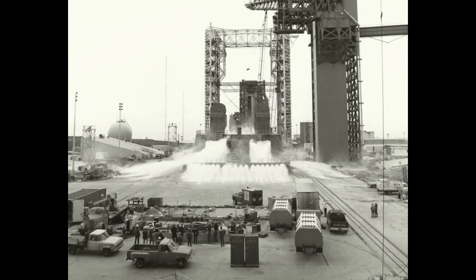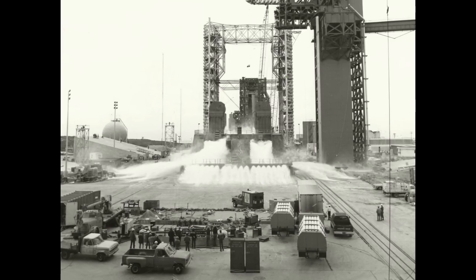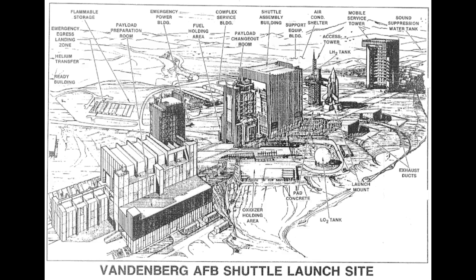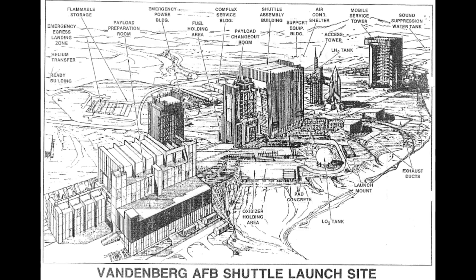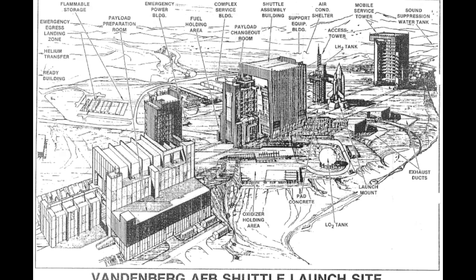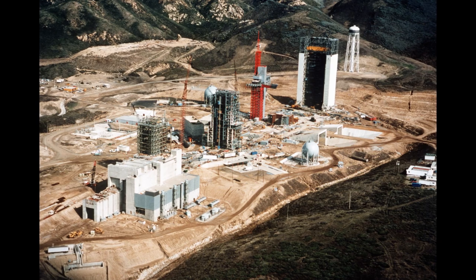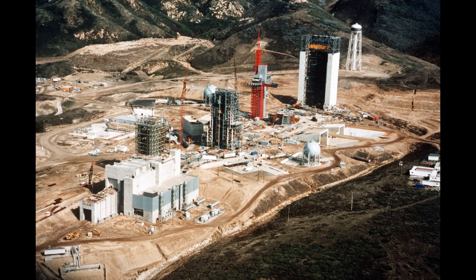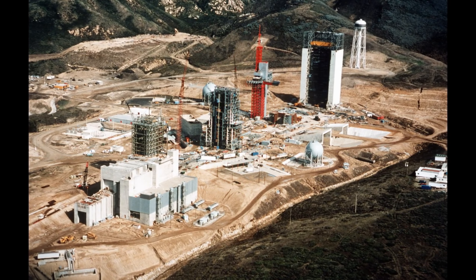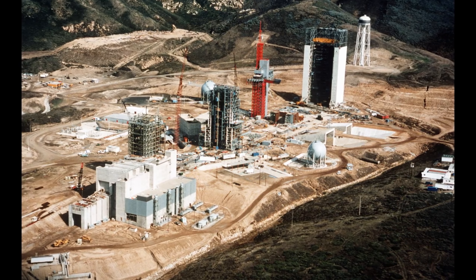There were a number of considerations to be taken when using the launch site. First, polar launches require more fuel expenditure, as Eastern launches are assisted by the Coriolis effect, and as a result, polar shuttle launches would entail a very hefty payload penalty. Launches also necessitated overflying South Carolina during ascent, and the discarded external tank would overfly both Russia and Canada. However, the Air Force insisted that expenditures at SLC-6 were justified for the ability to launch high-priority military payloads into polar orbit, and added that the partially constructed architecture allowed for reduced costs when building the shuttle complex.